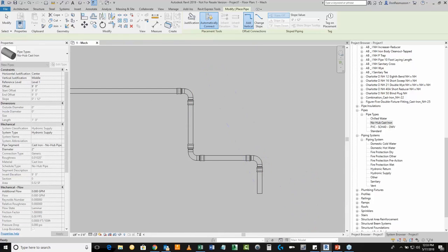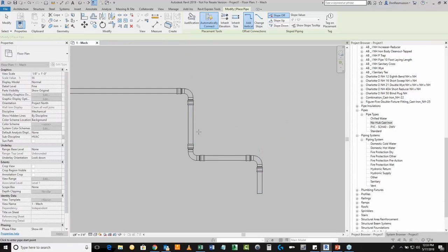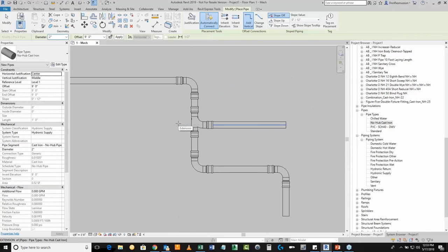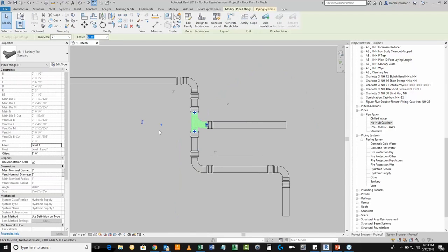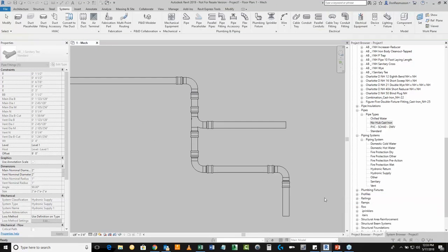Then we shift gears to the T's. So I'll draw a little jaunt off here. Let's make sure that that sanitary T goes in correctly. Probably helps if I draw a straight pipe though, guys, huh? Draw pipe straight, and there the T went in. Obviously I want to verify the T itself by clicking on it, seeing if I can swap this back and forth. It's the sanitary T, and things are a little bit different with specific T's, so it's not an easy swap, but it is flippable.